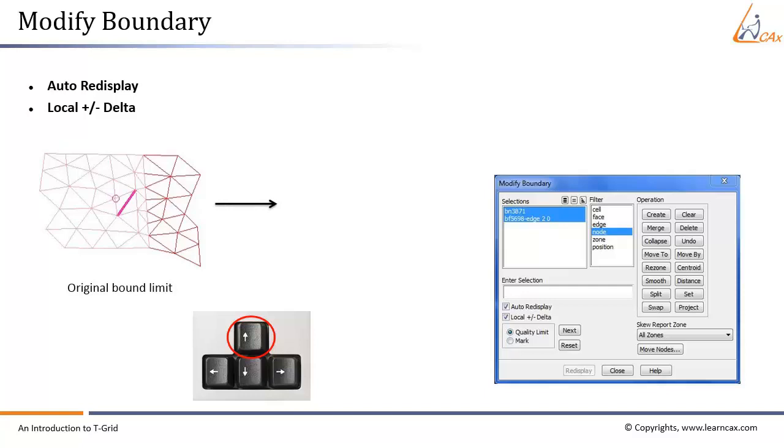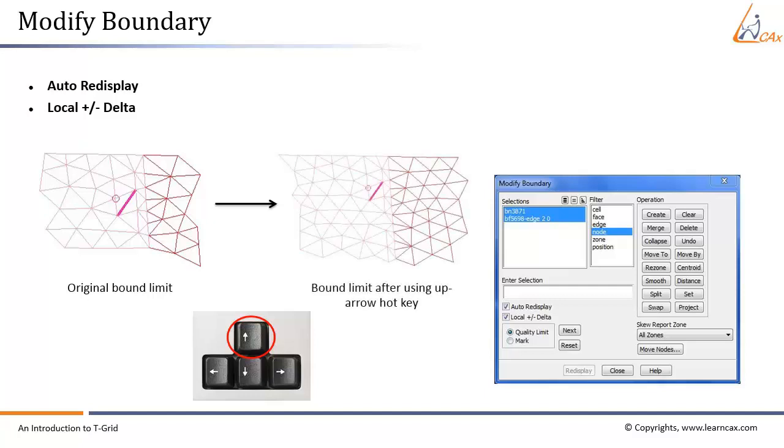In the graphics window, firstly, single-click with the right mouse button. Then, use the up arrow hotkey so that the graphics window will show skewed faces along with some of the faces around it. Each time you press the up arrow key, the layers around skewed faces will increase.